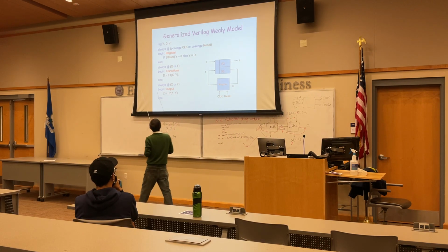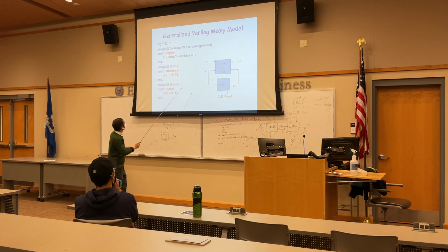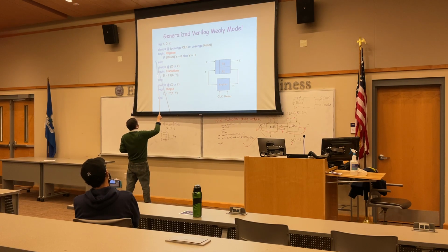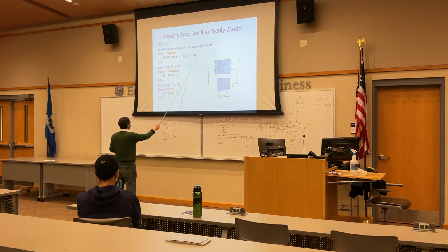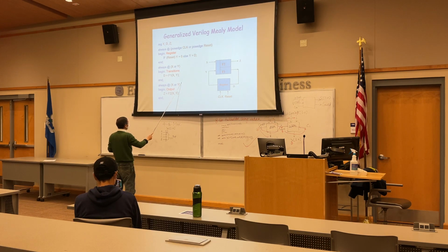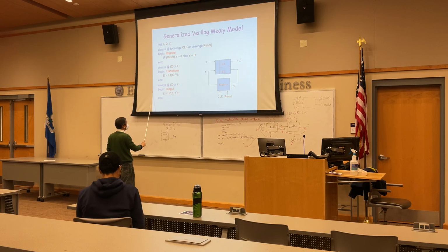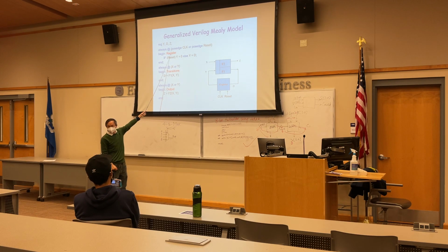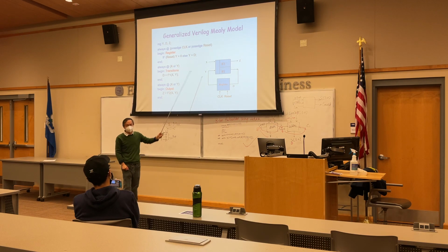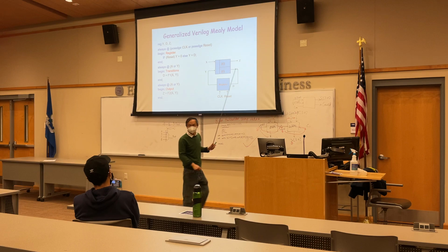Okay, so we divide it into 3 blocks. The register block; the transition block, which describes the STT; and the output block, which decides your final output function. This is reset. Transition is the description of your STT, and then general output. Is it okay? That will completely describe this sequential circuit.